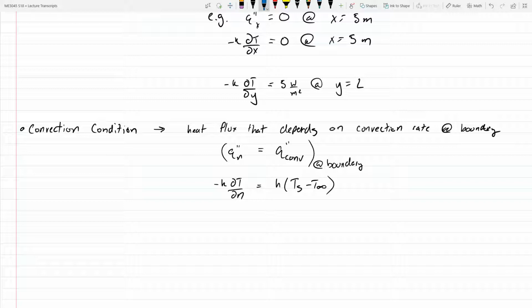Fourier's law is going to kick into action and say, hey, we've got a temperature gradient. Start kicking thermal energy away from the center of the block towards the edges to equalize it. And in response, you're going to start to dissipate energy from the center of the block out towards the edges and away by convection. But throughout this whole process, the surface temperature is going to decrease, okay?